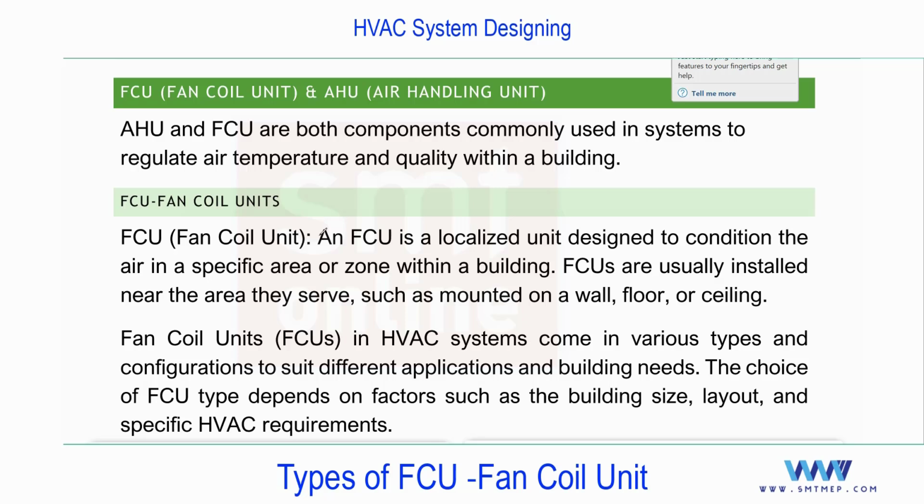But from a concept point of view, both belong to the air side, and both can be used for a cooling system or a heating system, depending on the type of coil or the type of system it is connected to. If the FCU is connected to a chiller, you can expect cooling. If it is connected to a boiler, you can expect heating. Or if it is connected to a VRF system, as we discussed in the last session, if it is a heat pump, you can expect cooling or heating as per the requirement, any one at a time, or heat recovery simultaneously. So this is common. First, let me complete this FCU.